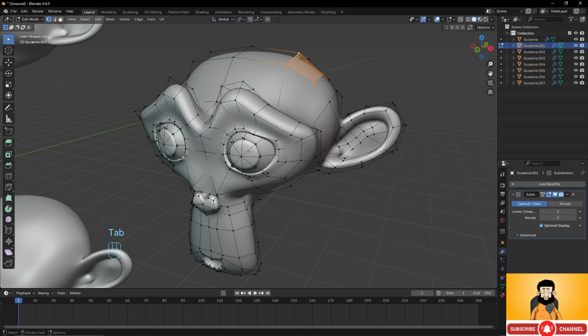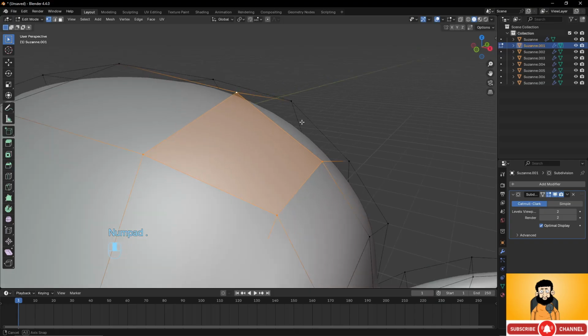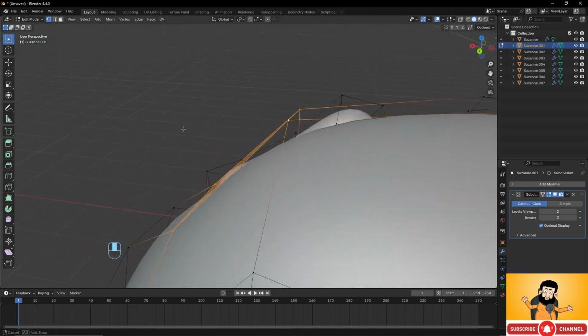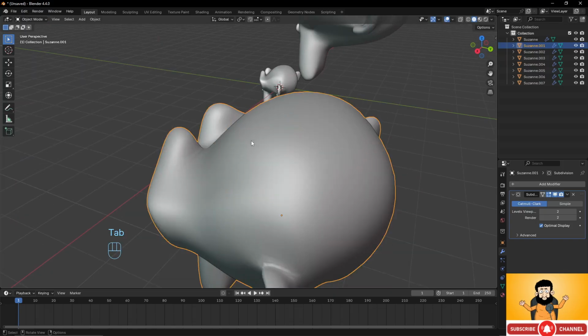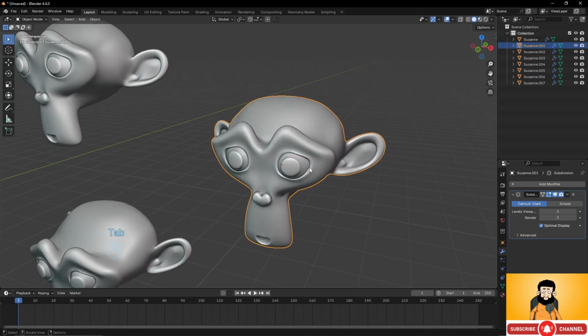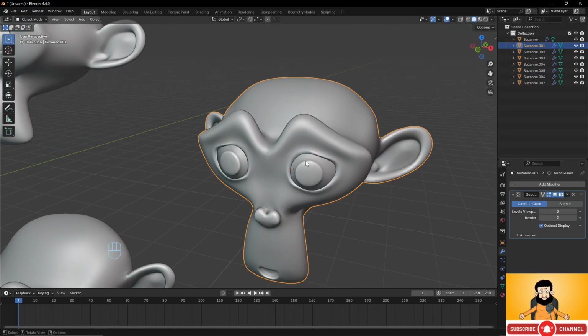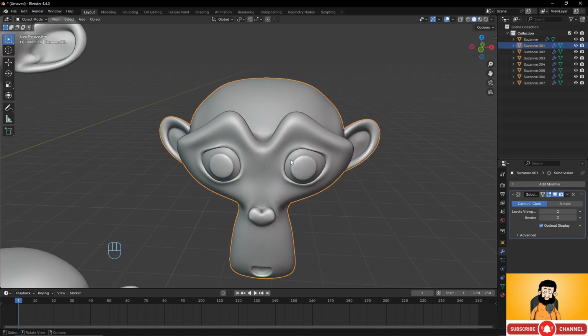So I can select here in edit mode and focus only on that face. As you can see, now I turn around this face only. It's very important to manage your view well. So when you want to go somewhere in your file and focus around this point, make your selection well and use this dot under the 3 on the numpad. It's the most important to navigate well.